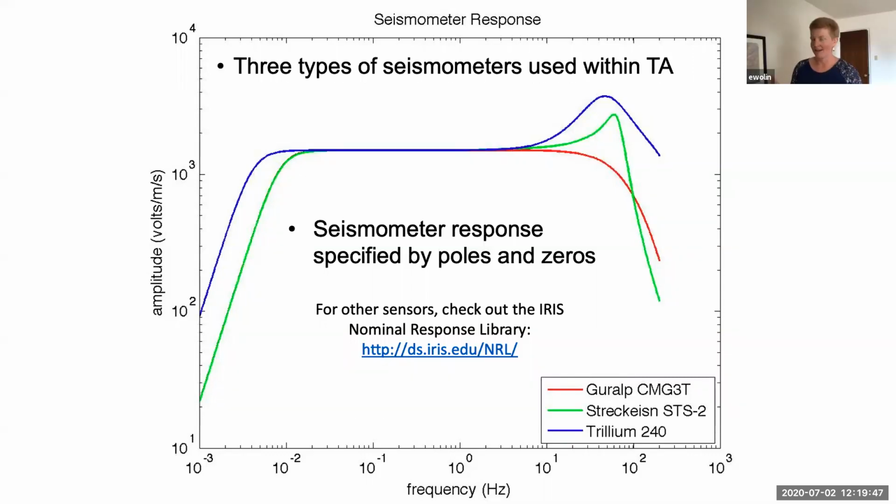Yeah, no problem. And so for this response exercise that we're doing, you could plot it up, and when you do your deconvolution, if it looks like you have a lot of long period noise in that 400 second region, even before the earthquake signal arrives, then you know that you're probably just blowing up ambient site noise when you do the deconvolution. Yeah, okay, that sounds great.